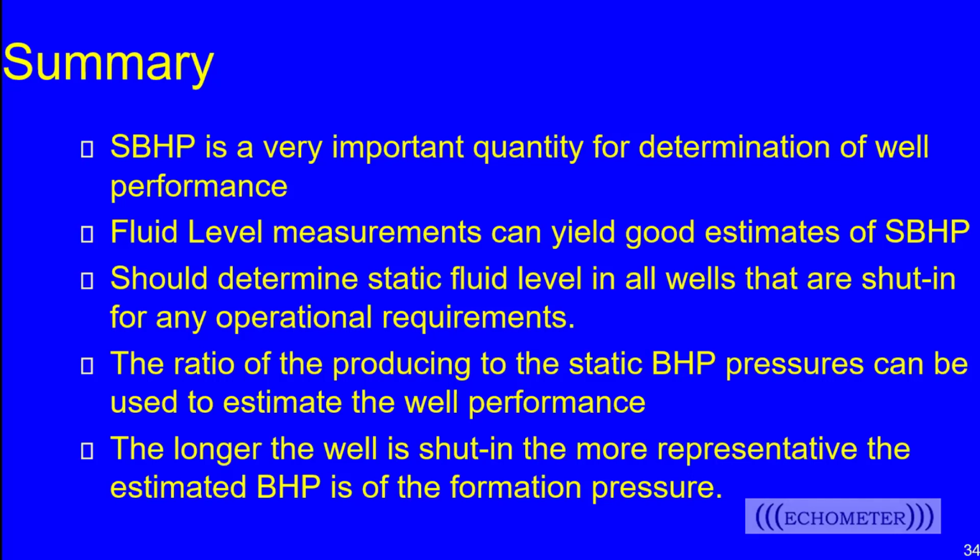Eula, I saw your comment there saying that it can take months on some of the unconventional wells in the Permian Basin. And yeah, those are tight shales, so a really tight well will take a long time to come up with that. Some of the more conventional wells, you might have it in a shorter period of time. I've seen it in some wells in a matter of hours, days, weeks, or even months. So, the way is just shoot fluid levels and see when they stop changing. Then you're at the static condition.